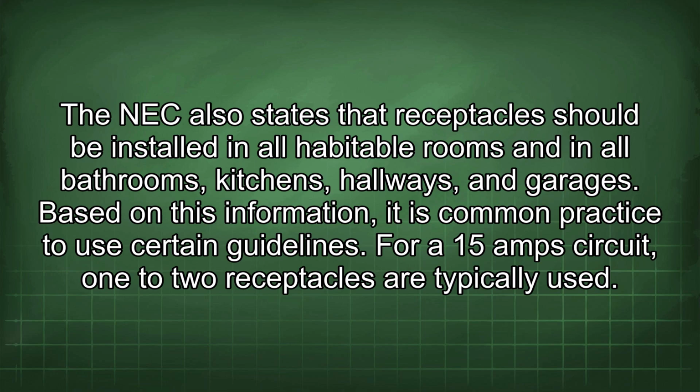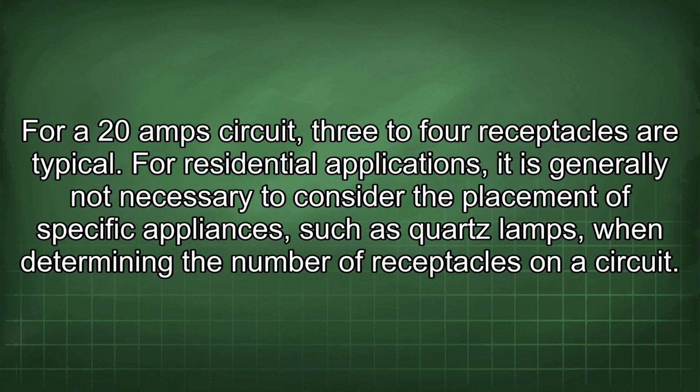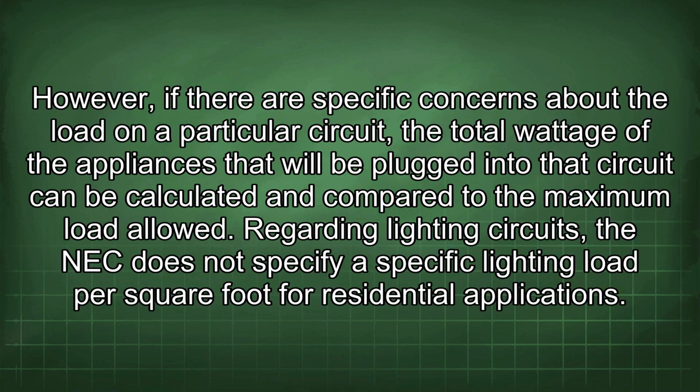For a 15 amp circuit, 1 to 2 receptacles are typically used. For a 20 amp circuit, 3 to 4 receptacles are typical. For residential applications, it is generally not necessary to consider the placement of specific appliances, such as quartz lamps, when determining the number of receptacles on a circuit. However, if there are specific concerns about the load on a particular circuit, the total wattage of the appliances that will be plugged into that circuit can be calculated and compared to the maximum load allowed.